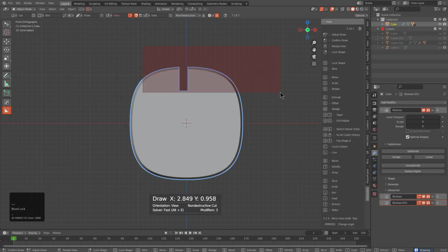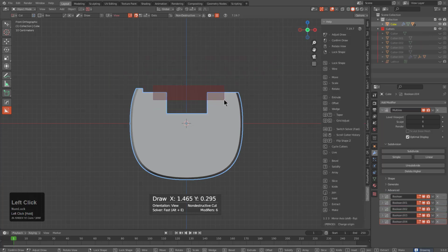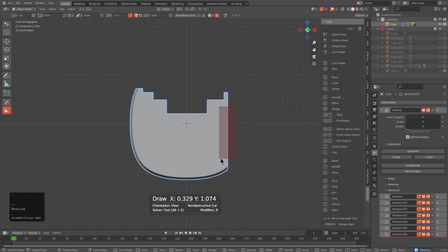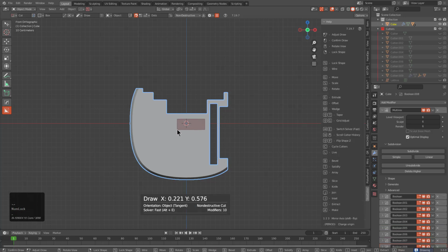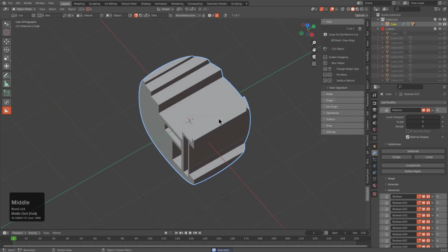And we see that you shouldn't even have to go in and modify any parameters in order to do this, but really you shouldn't be cutting a multi-resolution mesh with Boxcutter, since this is something generally reserved for sculpting. But for those users who just happen to use Boxcutter on a multi-resolution mesh, just know that the issue you were previously experiencing with it causing a canceled error has now been resolved.